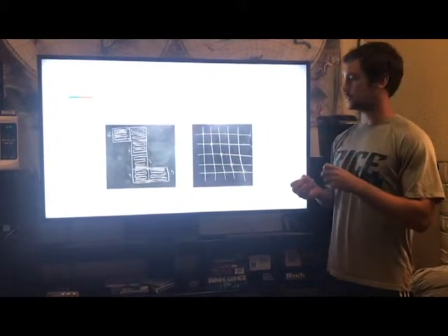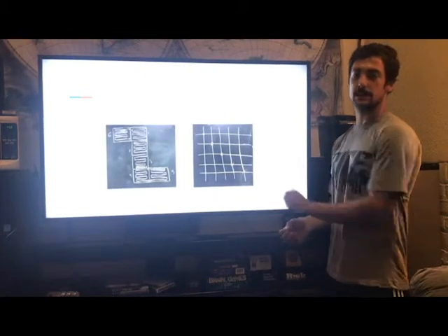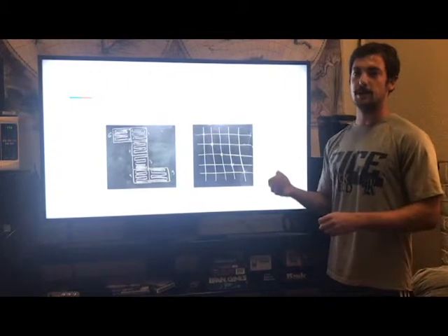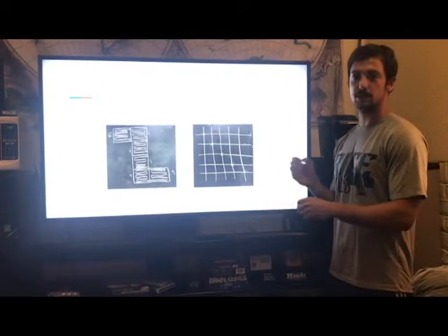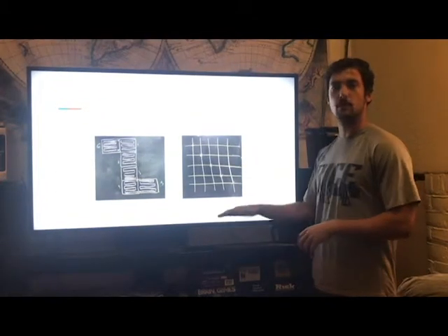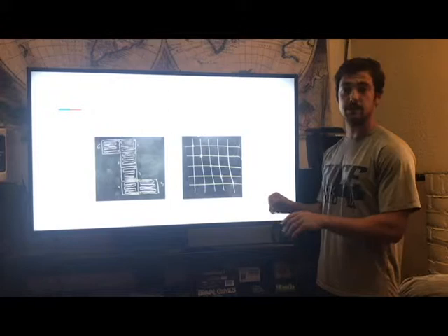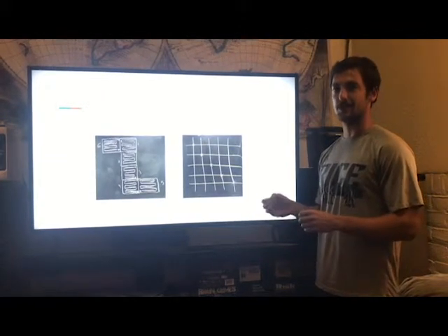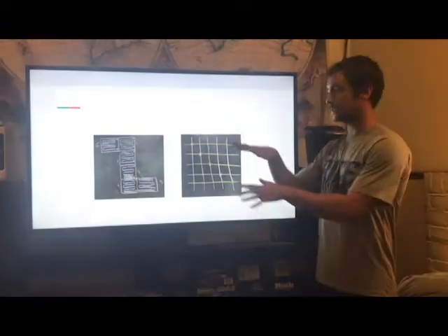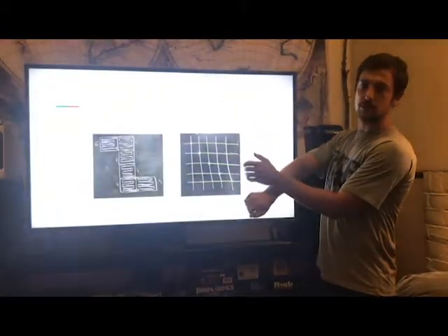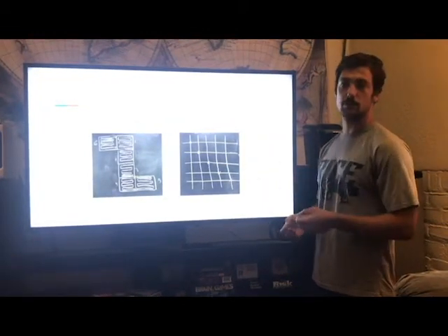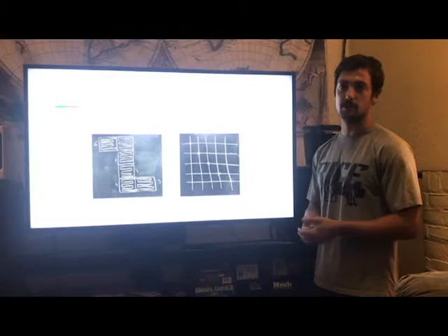Why this is important is whenever we interface 2 faces together, if we want the same corresponding left button or top button to be able to be read by the MSP, we would want it to be able to be accessed from the same pin. And going across interfaces or faces of the cube without having to use too many inter-wire connects or floating wires, having very specific arrays that we can then layer against each other so that each button could just be connected to the same vertical or horizontal trace using one jumper wire was very important for us.